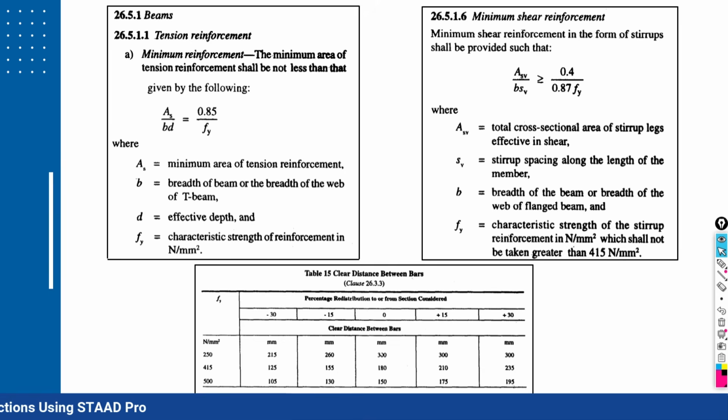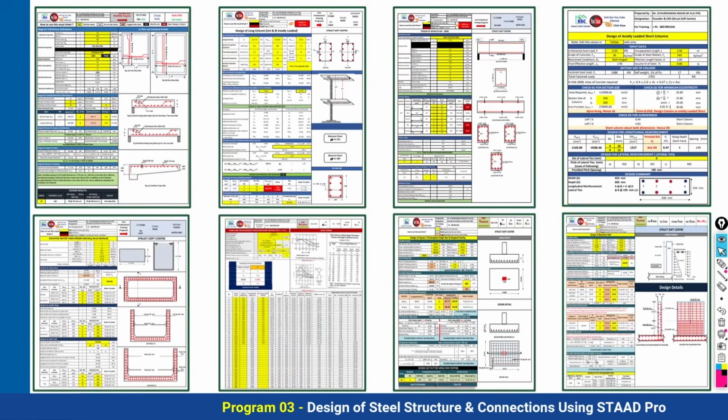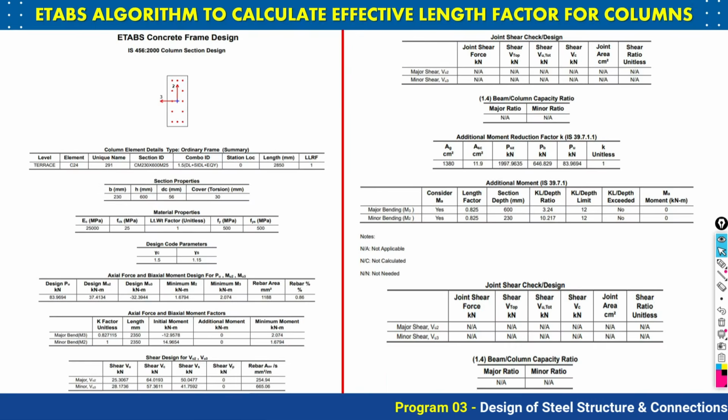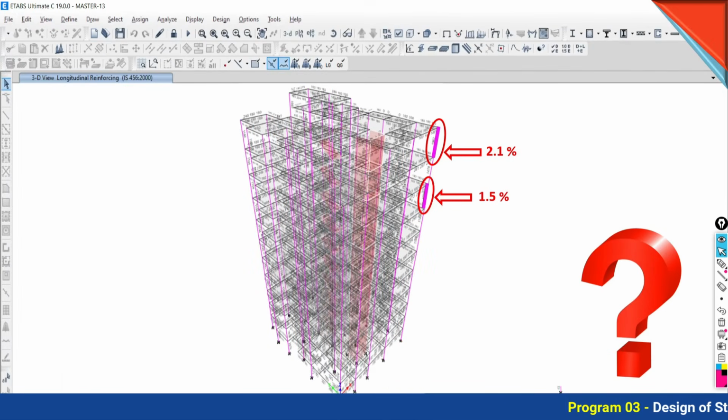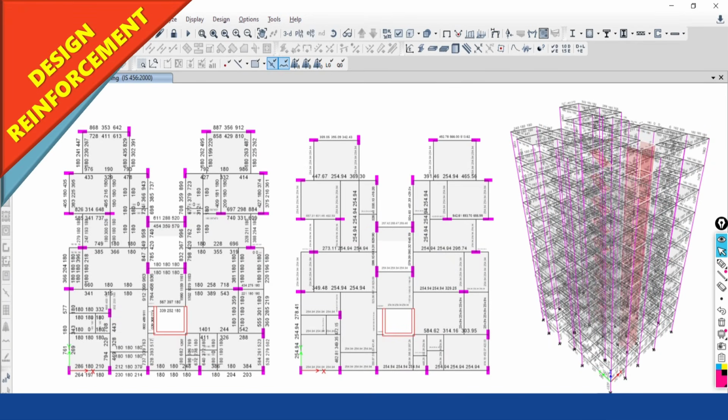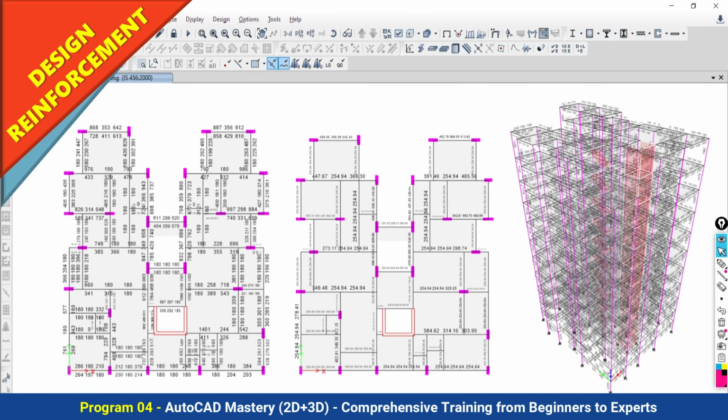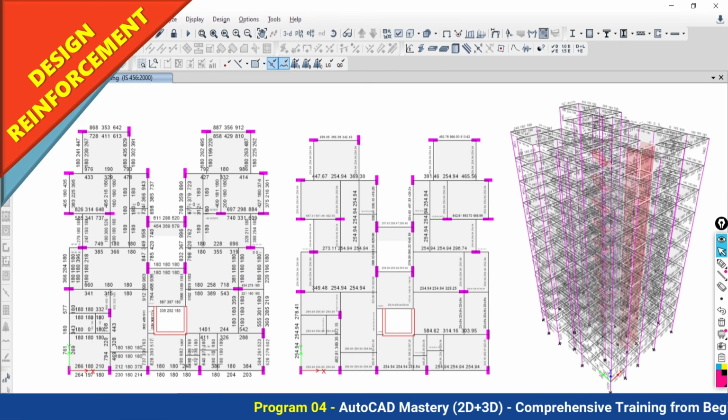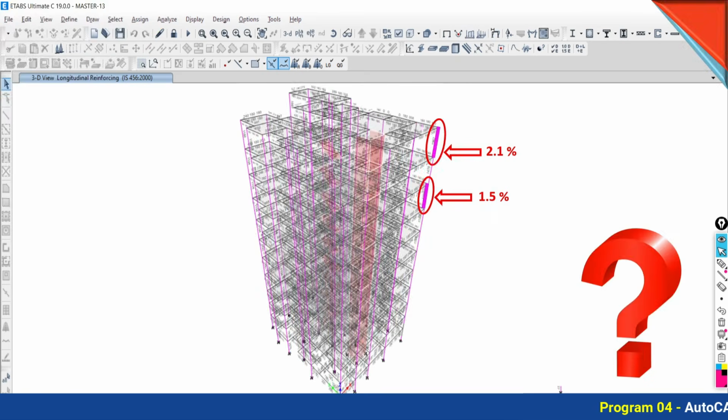Thereafter we are going to learn whether the Etabs software follows all the codal recommendations, codal considerations or codal demands for designing different structural elements and giving your design results. If any member is failing, what is the solution for that? By looking at the design results, we are going to prepare it. These are all things we need to do. There may be a problem at the modeling stage, there may be a problem at the analysis stage. We will do the correction for that, and then we'll come back to the design stage and complete our design.